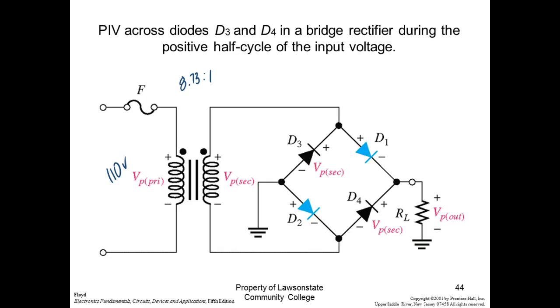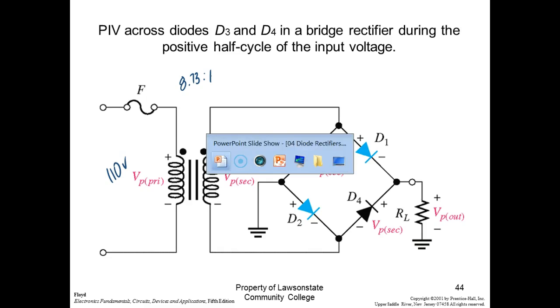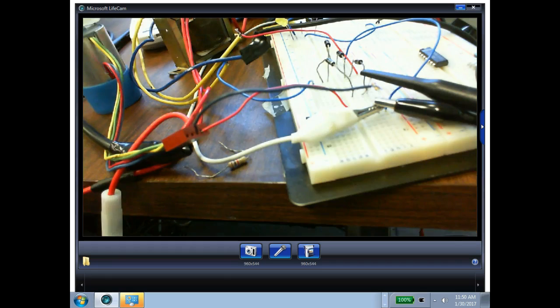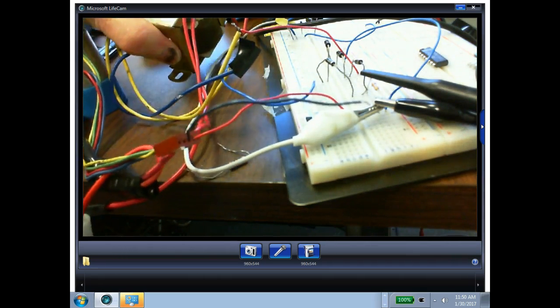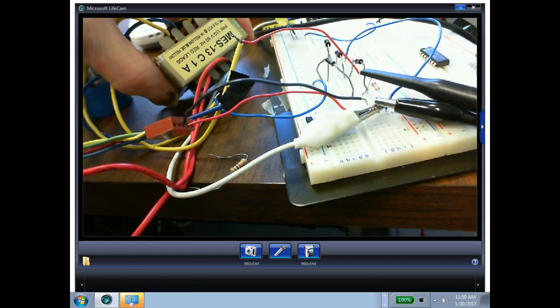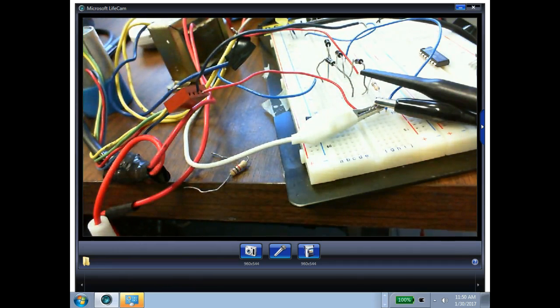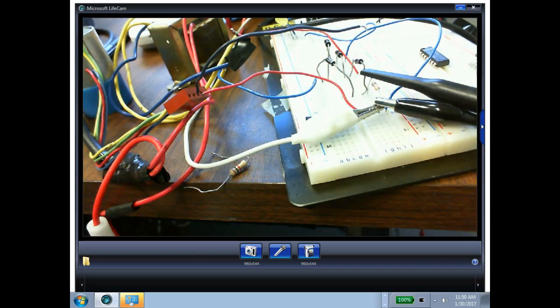By the way, commercial transformers like the one we buy, these little ones, sometimes they label primary and secondary voltage. So this one here has PRI, that's primary voltage, and then it gives you the secondary voltage. They'll probably have the color code on the label for what's the primary and what's the secondary. On industrial transformers, your big transformers, your high side is labeled with H's, and then the low side of the transformer is labeled with X's.